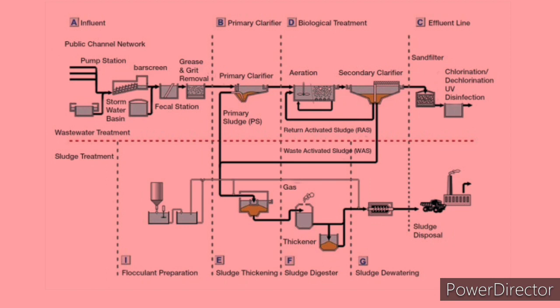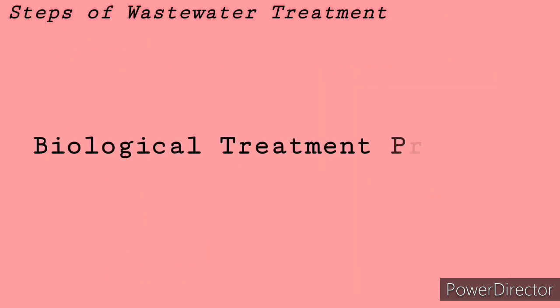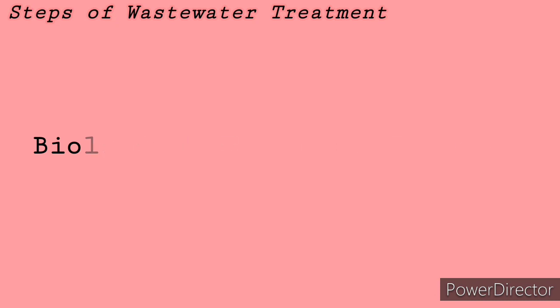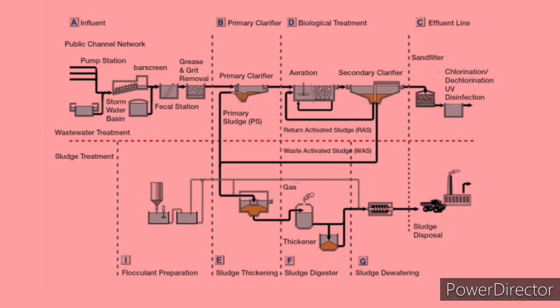So, in secondary treatment, we mostly have liquid wastewater. It doesn't carry any large or small particles because those are already removed during preliminary and primary treatment. In secondary wastewater treatment, we use biological agents like bacteria, fungi, or protozoa. This biological treatment takes out all those organic components present in the wastewater, and they use those organic components to grow themselves. In turn, they are reducing the amount of organic compounds in the wastewater, and that is really important.